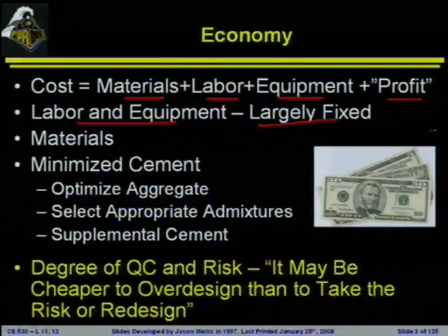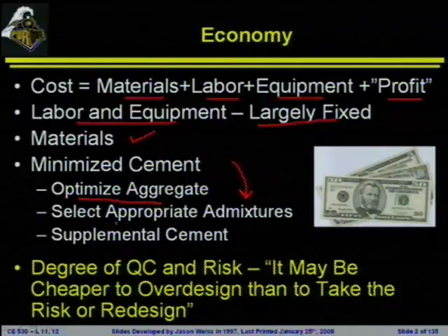The real goals that most people are trying to do is they're trying to obtain the best materials that they have locally available, and they're going to be trying to minimize the binder typically. Minimizing the binder because they want to optimize the aggregates. This will be good for most mechanical properties, but it will also allow them to reduce the amount of cement that they're using and typically save money.